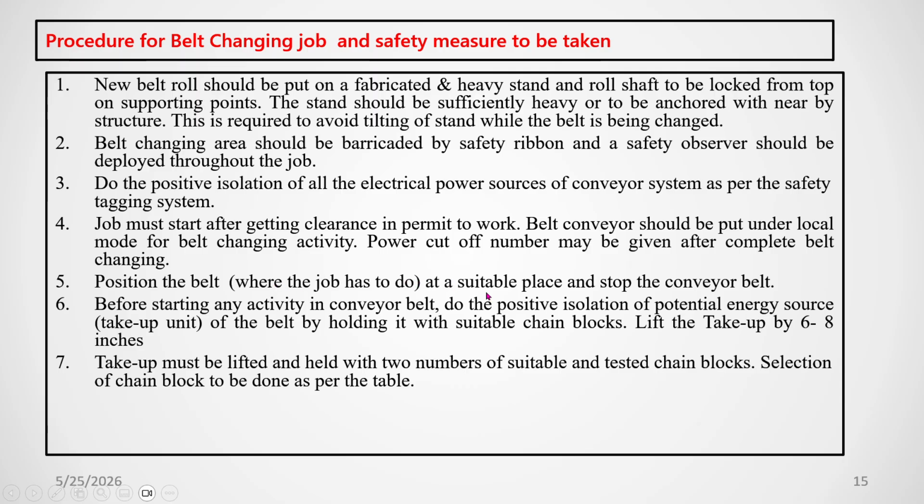That position should be located. Position the belt where it is placed, and stop the belt there where you can do the repairing job. Before starting any activity on the conveyor belt, do the positive isolation of potential energy sources like the gravity pulley.